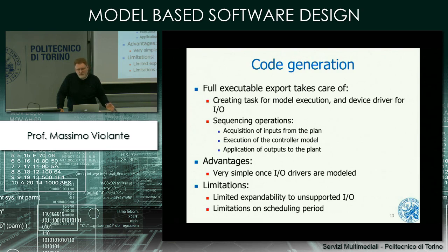Well, this is the good side of the coin, but there is a back side of the coin. The problem is that you have some limitations. For sure, you have a limited expandability because if you must use an I/O that is not supported by the platform support package, you are on your own. In the sense that you need to do some low-level programming, because you need to have this support for continuing using this development model. This is normally where the software vendor kicks in, and so they charge you engineering services to make this implementation for you.